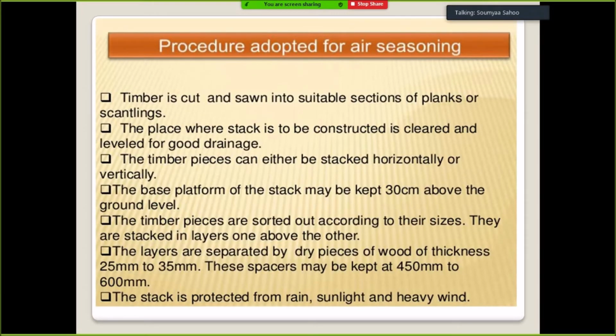So the timber is cut and sawn into suitable sections of planks or scantlings. The place where the stack is to be constructed is cleared and leveled for good drainage. The timber pieces can either be stacked horizontally or vertically. The base platform of the stack may be kept 30 cm above the ground level.